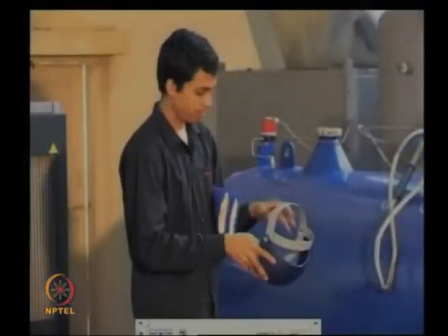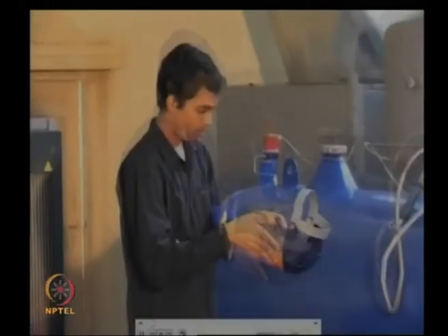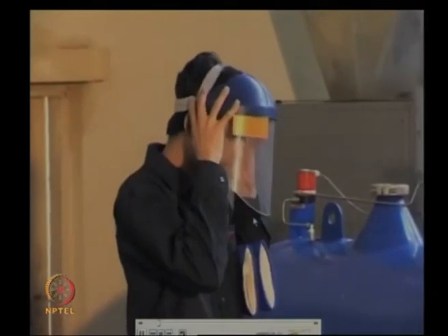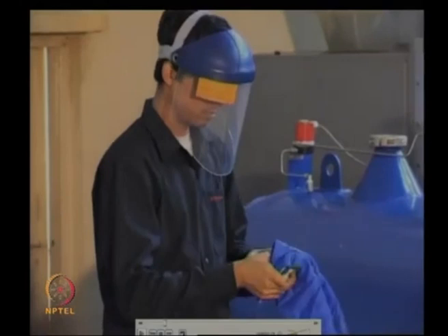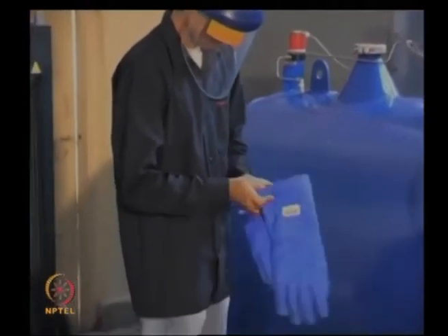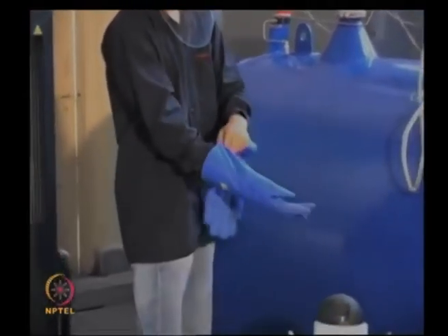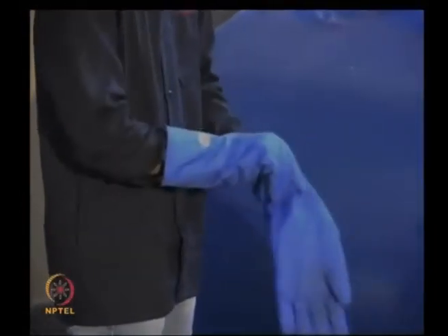You can see all these protection devices that are used in our laboratory. What you see here now is our engineer Suraj, who will show you how we transfer liquid nitrogen from our plant to a cryo container. You can see that he is handling a face shield, and this face shield will ensure the safety of your eyes and body parts. And again, he has specially made gloves for nitrogen operation, which work at low temperature, and these gloves are lined with an important material made specifically to act against low temperature for your hands.